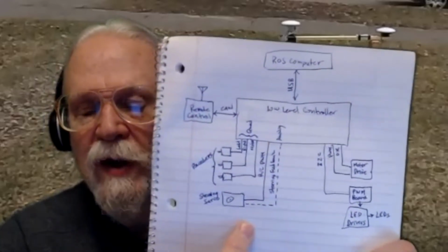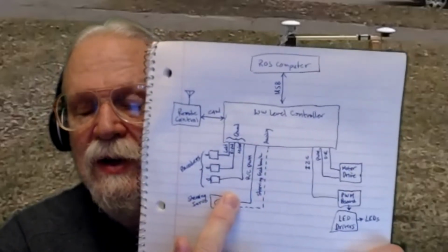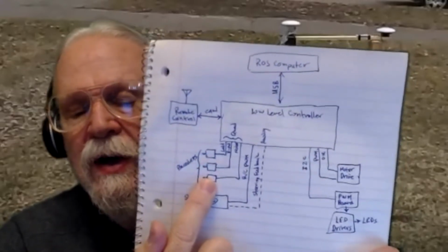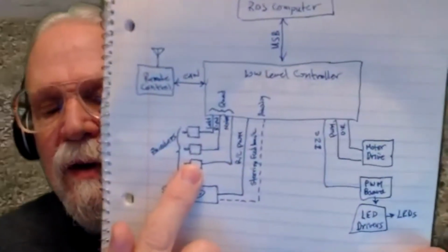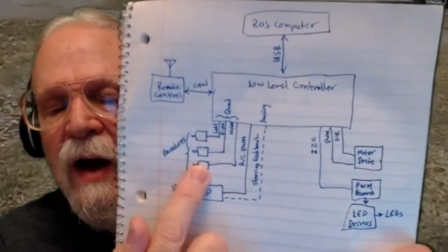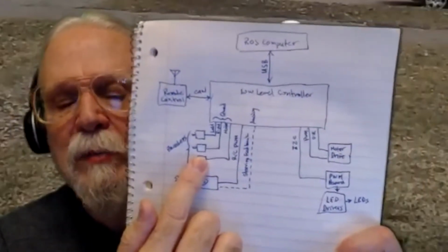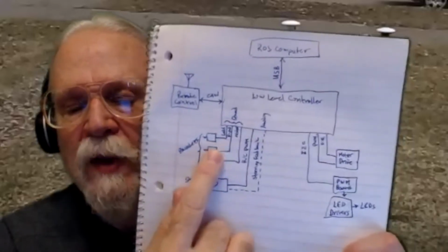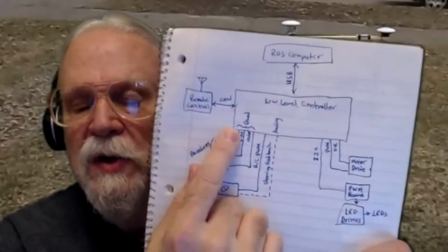But all the things down here where I've got the pieces, here's the RC servo. You just generate a PWM signal for that, so that's just a single control line, not a communication. Then I've got my three encoders, one on each back wheel and one on the motor itself. I don't know how these cameras focus. Later, if I do this, I can take a picture of my camera and post it so it'll be readable. Each one of those has two wires that feed into the board to do quadrature decode. Again, those are signals, not communication lines.